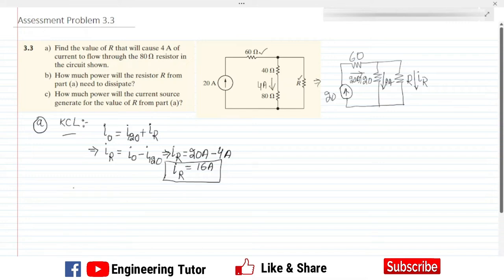After finding it, we can use the current divider law. According to the current divider law, the current through R is equal to the value of the resistor at the other end, 120, divided by 120 plus R, multiplied by the total current. The total current here is 20 amps.